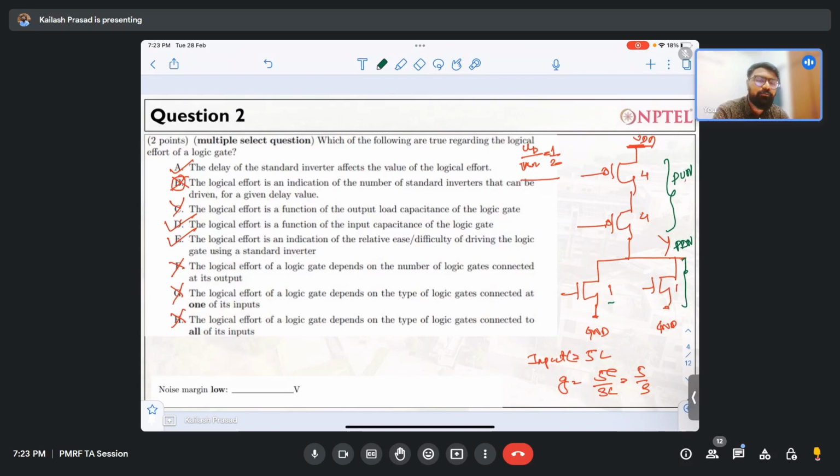So what we will do is start with the minimum width which is available to us. Whenever two transistors are in parallel, you have to focus on one path and then focus on the other path. So I will forget this particular path for now, and I will put 1 over here. If 1 is the width, then R of NMOS is directly proportional to W, so it is 1 times W.